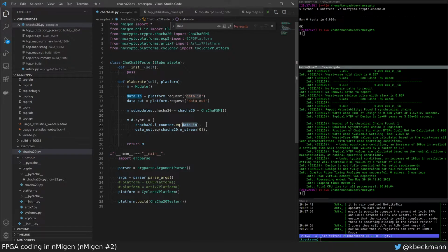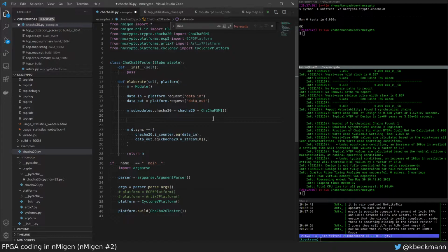So if the tool is smart enough, it can essentially simulate the whole circuit and try it out with a 0 here and a 1 here and see what the output becomes. So I suppose maybe the tool was too smart, which means that we need a shift register to fool it. But this can help us to create a test bench that makes sense.